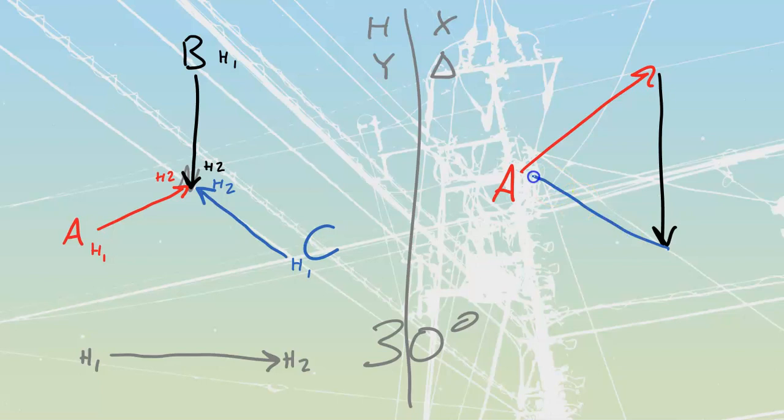Two seconds. Okay, now that we've got this, we can put in our lines. So, sorry, that's a C line over here and a B line over there. And then I'm going to label everything. I see that the tails are going to be the ones, but now we're low voltage, so this is going to be an X1. This would have to be an X2. This one is going to be an X1. This one's going to have to be an X2. And this one's going to have to be an X1 and an X2. Okay. We have now got a proper configuration to go from my high side Y over to a low side delta. Let's place all of these drawings now.